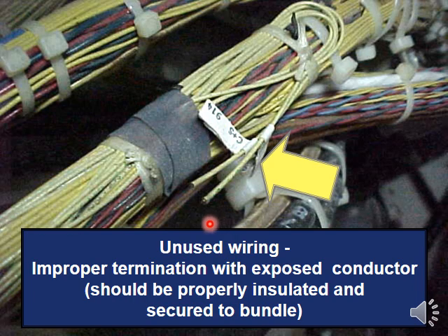So notice this picture. This wire here is breaking all 3 of the rules. First of all, the copper. Is it exposed beyond the insulation? Yes. Now, is there a cap on top of this wire, or is it free and open? Obviously, there's no cap. And finally, is this wire bundle secured with the rest of its friends here in the bundle? No. These strands are left open and free, so all 3 rules are broken. Naughty.